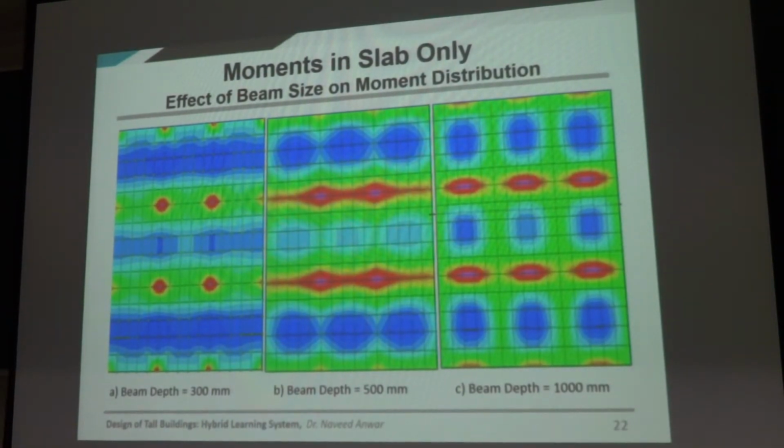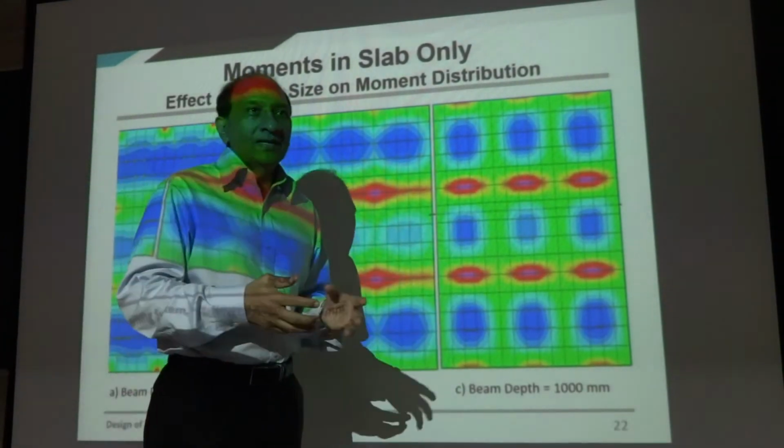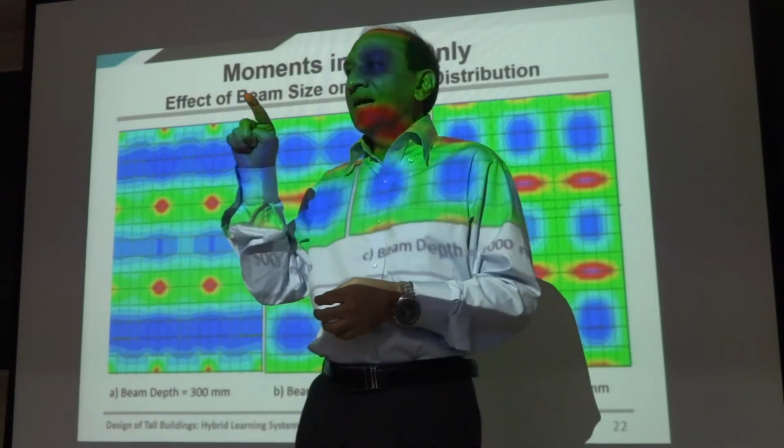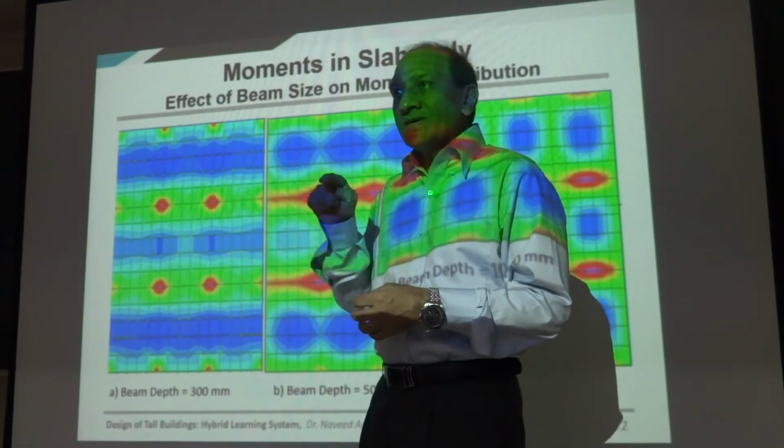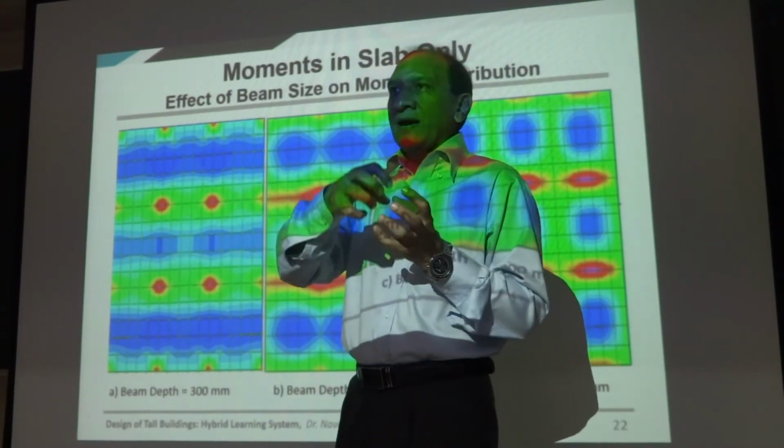Only distinction is beam comma slab. So all systems which is beam dash slab means where the beam and slab act together to carry the load, we call them beam dash slab. And beam comma slab is when the beams and slab are different and the slab is supported on beam.